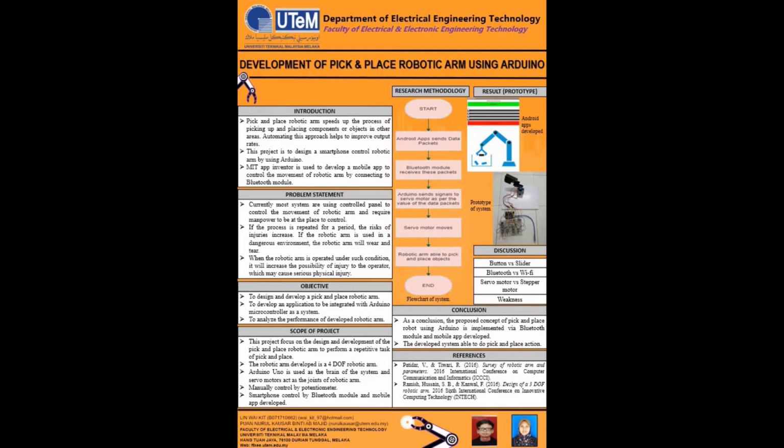And last, because of the quick reactions to disturbance, the servo motors are best suited for synchronized motion, while the stepper motors may be slower to respond to the disturbance. Besides, servo motors have high torque levels at high speeds, something that stepper motors do not have. In AC or DC drives, servo motors can operate and do not suffer from vibration or resonance problems.